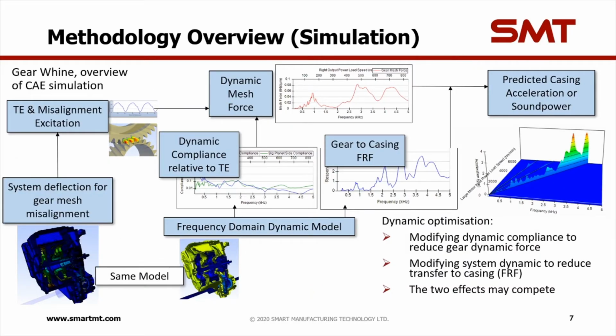Okay, so in a bit more detail, we start off with the system deflection to predict the mesh misalignments. This is then used in the loaded tooth contact analysis calculation to predict transmission error and shuttling forces.